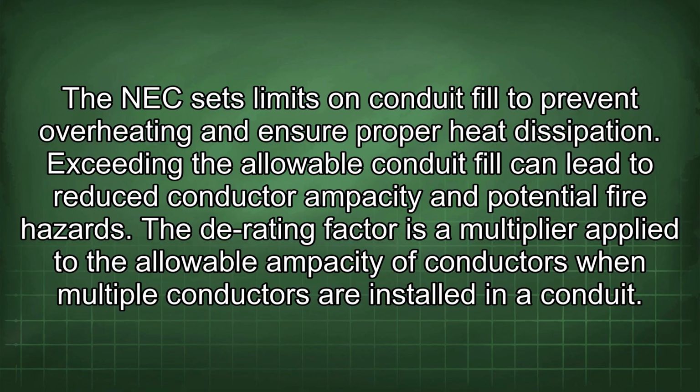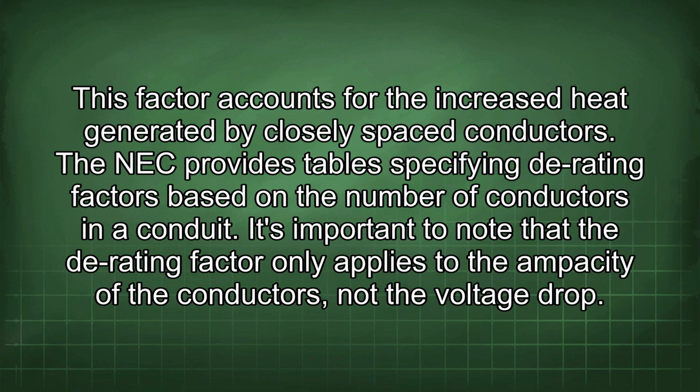The derating factor is a multiplier applied to the allowable ampacity of conductors when multiple conductors are installed in a conduit. This factor accounts for the increased heat generated by closely spaced conductors. The NEC provides tables specifying derating factors based on the number of conductors in a conduit.